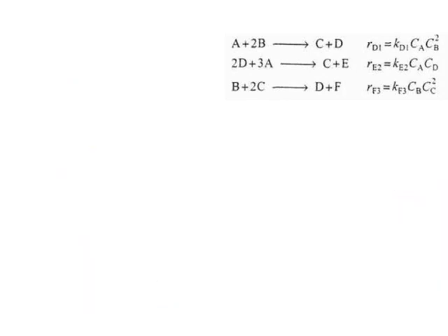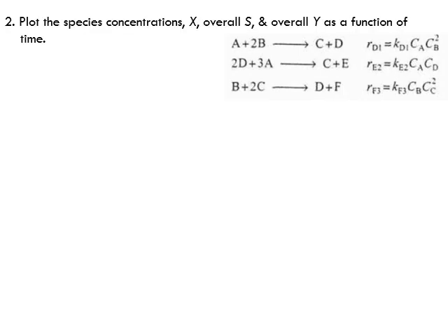What else do we need? We said in these design equations, V is variable. So how do you find an equation for V? We use mass balance, correct? The mass balance states that m dot in minus m dot out equals dm by dt. The mass coming in is rho naught times epsilon naught. Do you have any mass leaving? No, we don't.